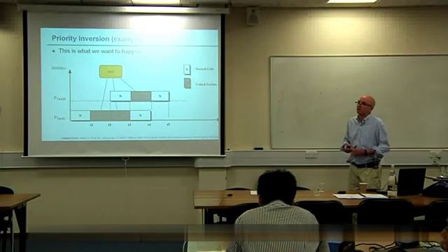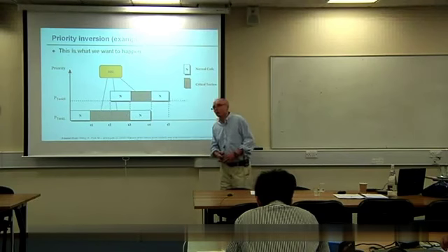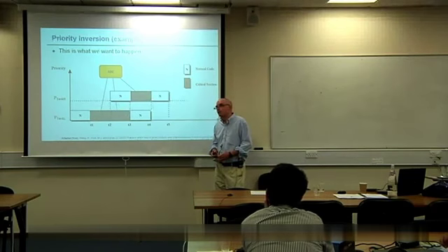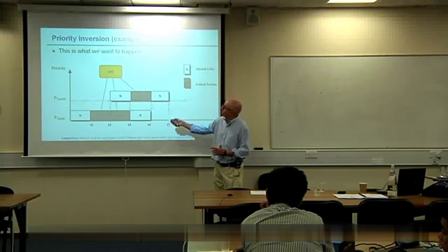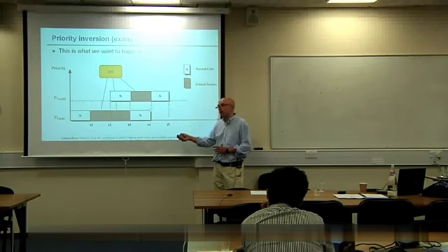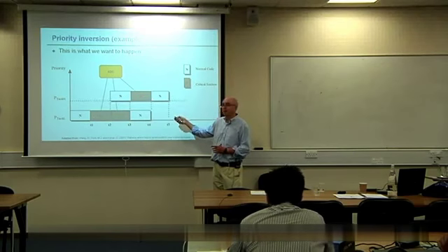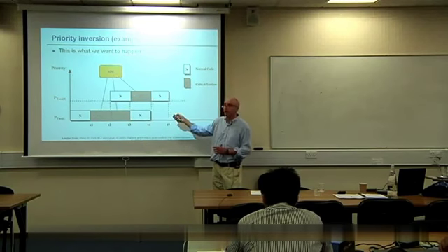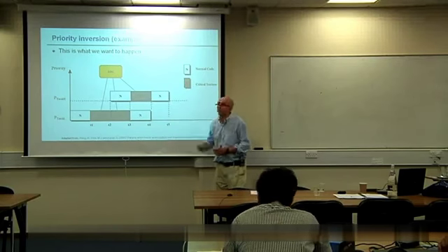You need to look at where it does the existing. Well, how could you determine, in this setup, does this task need to have infinitely high priority? It might do, like if it's in a car and it's a brake pedal or something, you want it quite high. Well, to avoid the clash here, all it needs to have is a priority equal to that, so that it can run. And it needs to have a priority equal to the highest priority of any task which accesses that critical section.